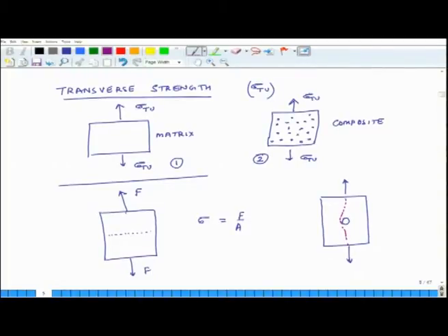So, in the first case the stress lines were uniformly distributed, but here there is a stiff material at the center, and because of this the stress lines flow in a way so that they get concentrated around the edge of the object, and as I move far away from the object they again become uniformly distributed.